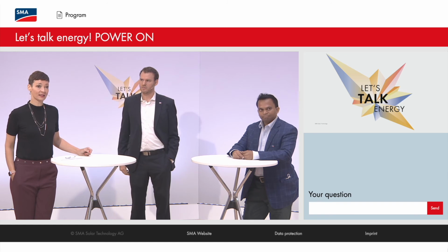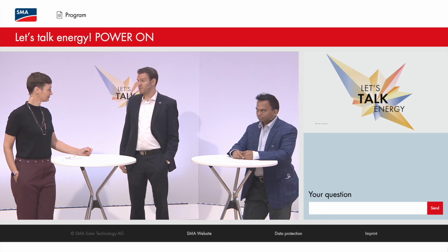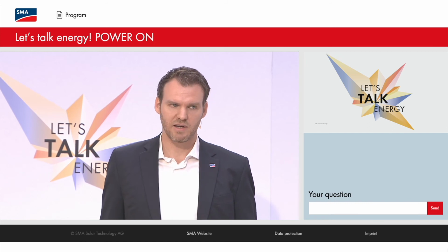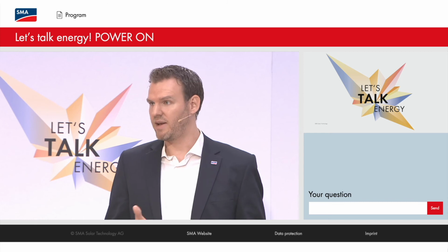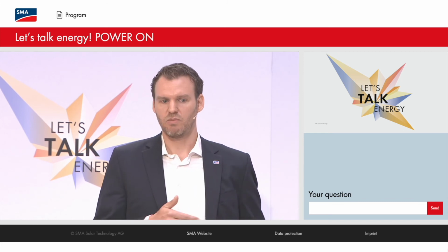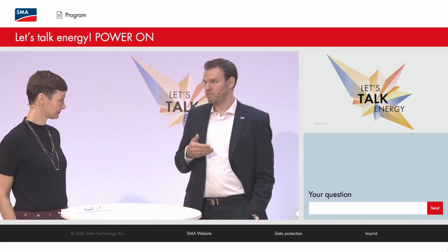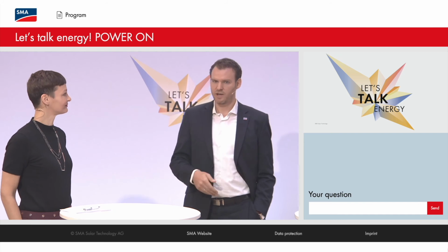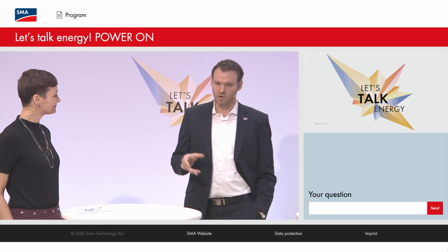So, next question is how do you design a central inverter system? Strongly depends on the market. There's not a general rule which you can apply everywhere. We've seen many markets now, especially desert-like locations where there's more or less unlimited land, but a limited grid connection. So you basically start from the back end. So you start with how much energy am I actually allowed to feed into the network? Let's say this is 100 megawatt. How much additional reactive power do I need to provide? At what temperature, etc. So you really start from the back end, and then you start going forward.